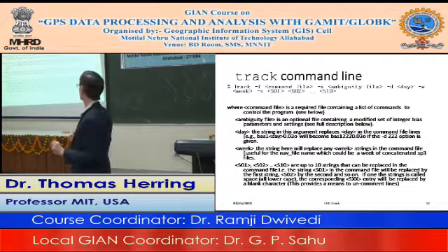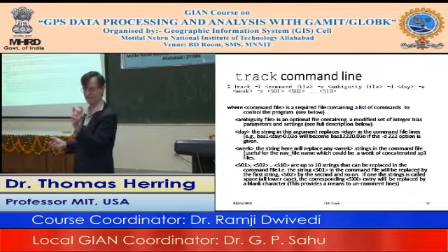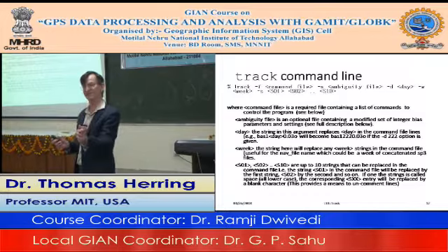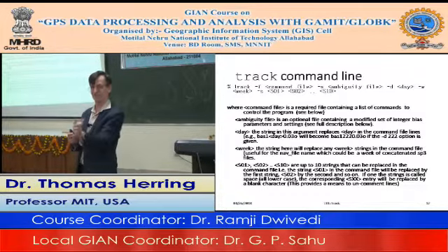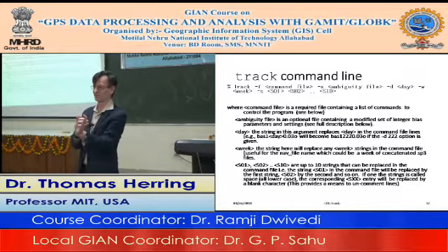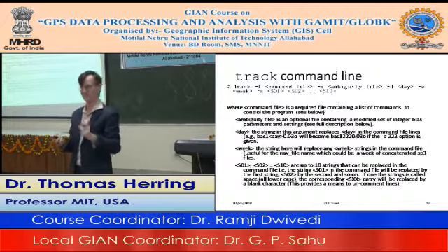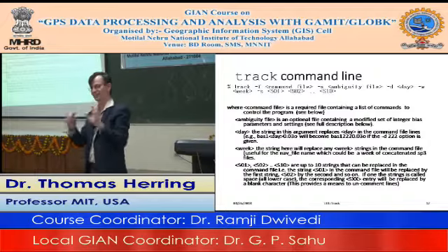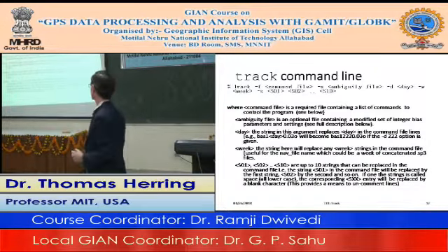One special case in here is you can make this the word space, S-P-A-C-E, and it will replace that string inside the command file with a space. If you remember the way the commands work, where any non-blank character in the first column makes it a command, this is a way to have something be a command in some cases but not be a command in other cases. So again, it gives you a lot of flexibility if you think about how you want to set up your solution as you go across.